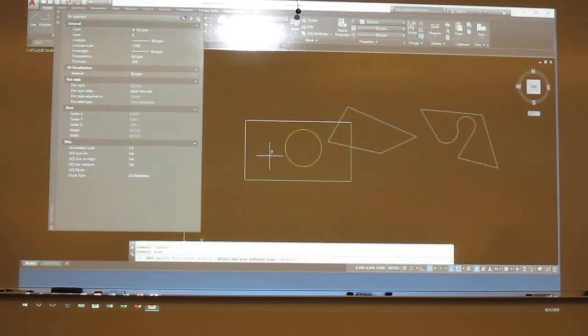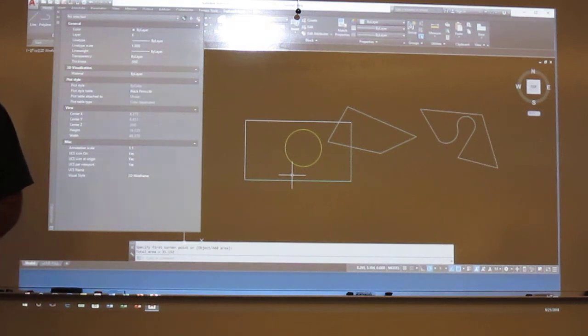Come back in. I actually ought to add some. So I'm going to say add this one. Hit enter, and then I'm going to subtract this one. And I'm going to use an object on this. And then it will do the math for me. So you can do that also. So I know that's the area, it's 31.15. If it's so far deep, I just times it by that, and hey, I've got the yards of concrete that I need to order.